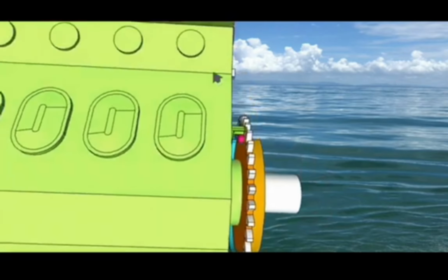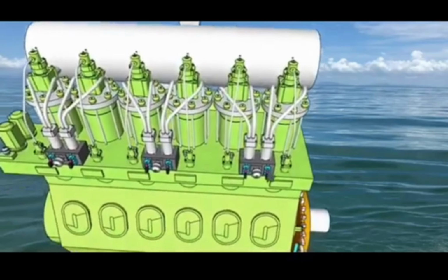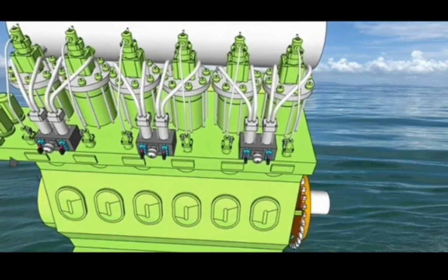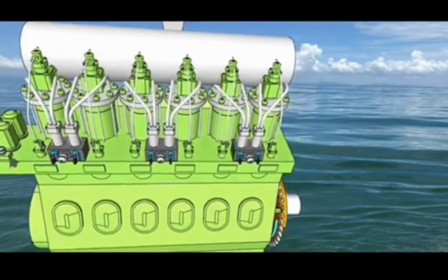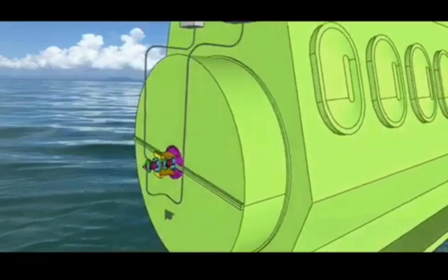The next setup is the hydraulic control unit. For 2 cylinders there is 1 hydraulic control unit, which accommodates 2 fuel pumps and the electronic fuel injection valves plus cylinder lubrication. These are the high pressure pumps fitted, and all the high pressure pipes are fitted inside the crankcase for safety reasons, so no high pressure pipe is outside. That is very important, and this is the accumulator for giving a stable hydraulic supply.